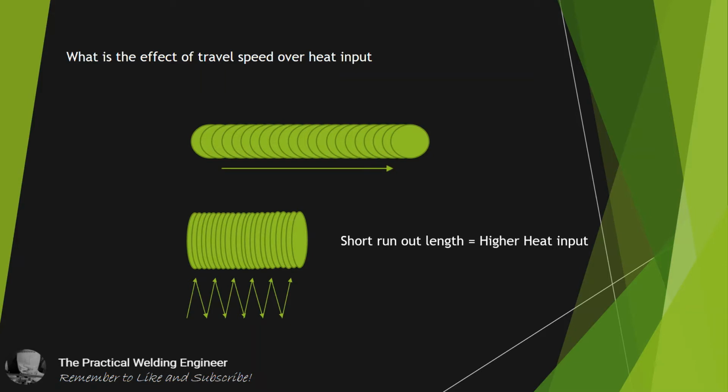So if you find that your welders are either too low on the heat inputs or too high, of course the easiest thing to do is get them to either speed up or slow down. That will have a drastic effect on the value that you start to measure, more than changing a few amps or a half a volt will get you.